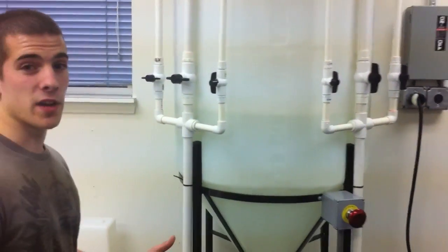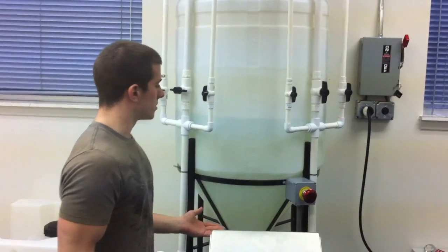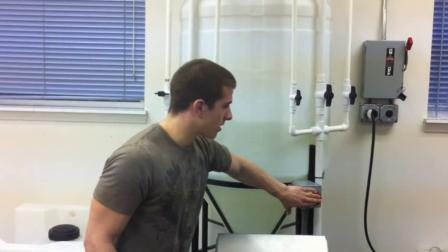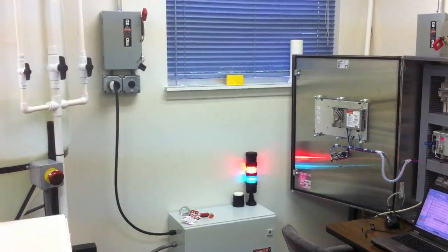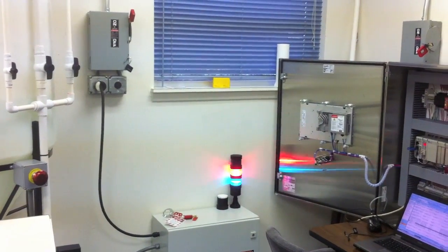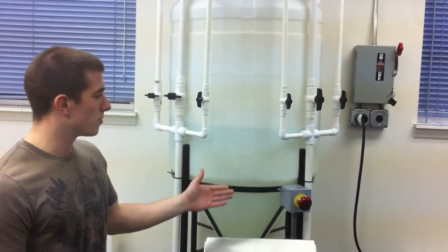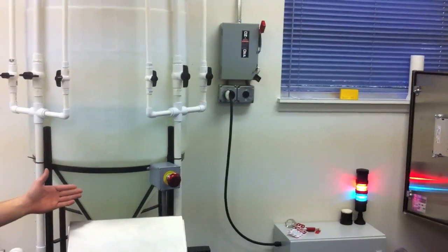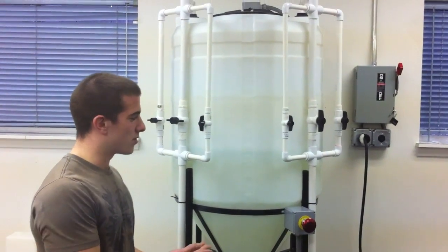In case of any emergency in the system, what either Luke, Trevor, or myself would do is come over to the emergency stop button, press that, and immediately see the red and blue stack light come on, and the pump stops. So that just shows that there's something wrong, so the system will stop. Normally there's a horn in there, but due to the loud nature of the horn, we don't want to disrupt any employees here at Process and Data Automation, so we put in a blue light.